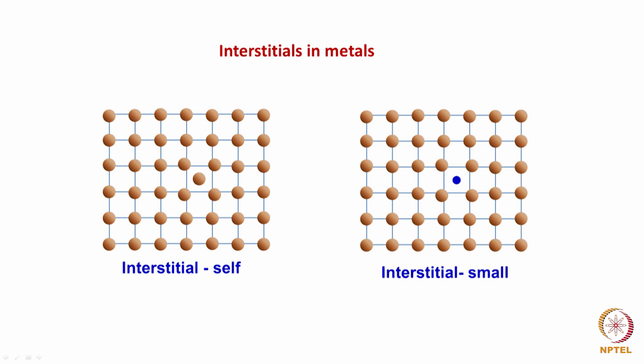When they occupy the interstitial position, we should understand that they may still create a small distortion around it, depending upon the type of interaction which it has with the neighboring atoms. There could be a repulsive force which may move the atom away, but the extent to which atoms are repelled from the lattice sites may be less.